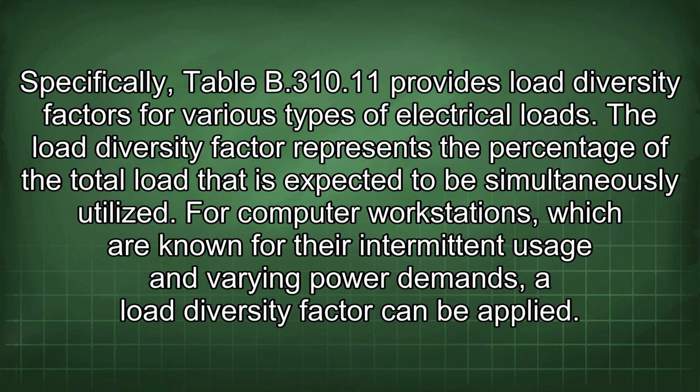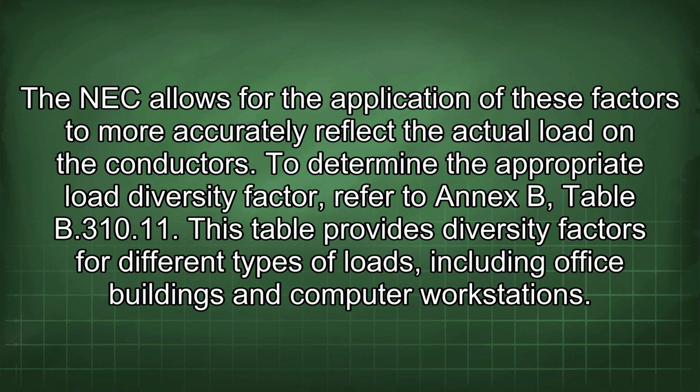The load diversity factor represents the percentage of the total load that is expected to be simultaneously utilized. For computer workstations, which are known for their intermittent usage and varying power demands, a load diversity factor can be applied. The NEC allows for the application of these factors to more accurately reflect the actual load on the conductors. To determine the appropriate load diversity factor, refer to Annex B, Table B 310.11.